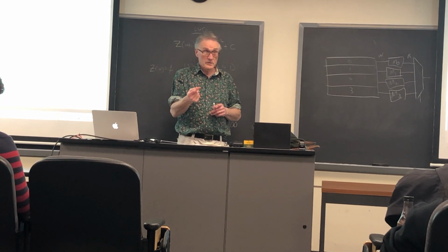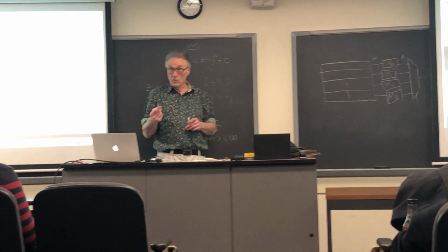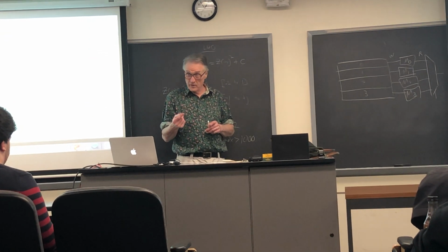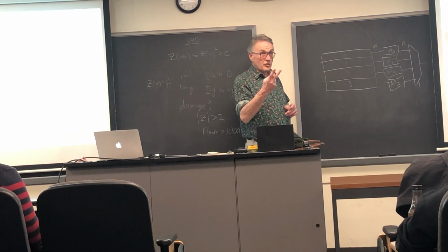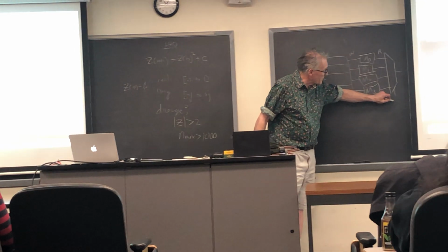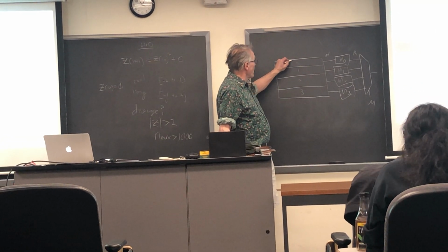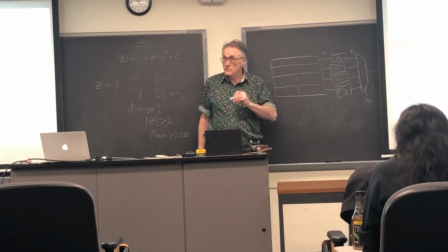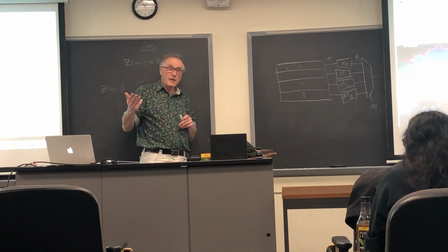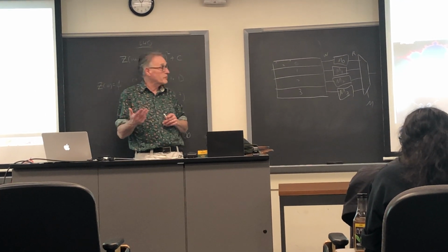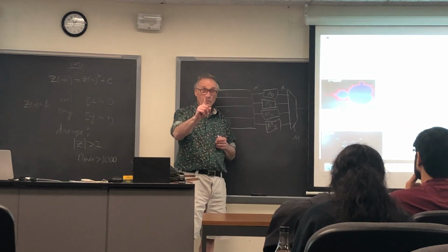What you're going to do here is produce an address. The VGA controller that you're going to be using produces an address that you write, 2 bits of which will determine the muxer, and the other bits will determine where in the image it is within that stripe. So you'll give it a 19-bit address, or 20-bit address, and what will come back through this muxer is a color for the pixel you need.